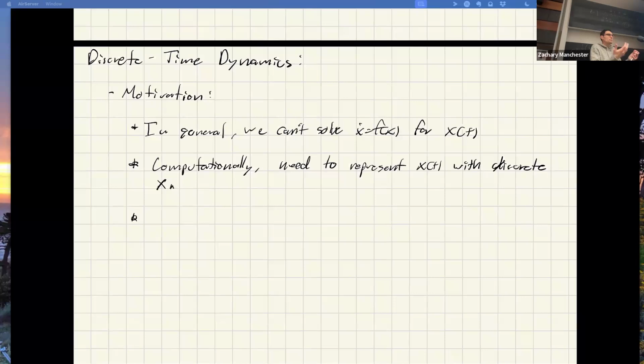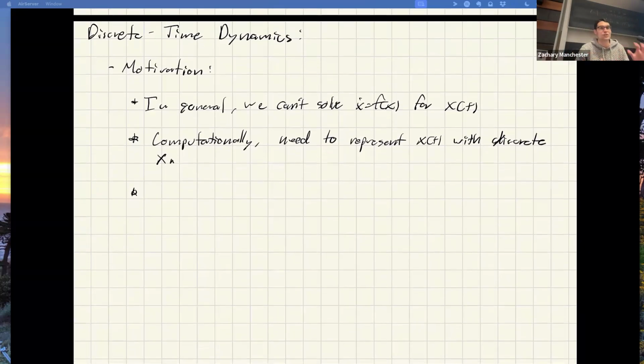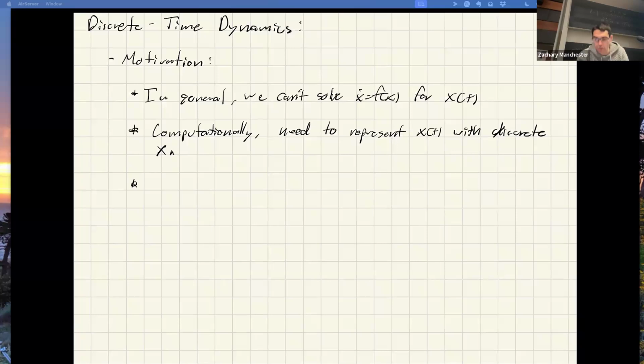If I'm really being serious about rigid body assumptions, and I slam a rigid brick into the ground and it just stops instantaneously, the velocity went from minus whatever to 0 at the instant it hit the ground. So what's x dot then? Or x double dot? Accelerations are infinite, right? It does weird things. So strictly speaking, you can't simulate impacts and similar things with an ODE without extra hacks and tricks. So that's another reason why this discrete time stuff is very relevant to us.